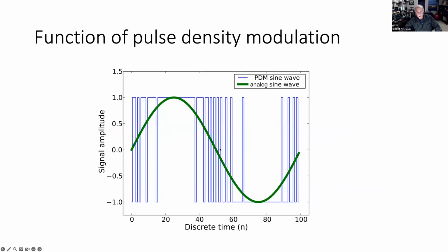So again, this is another view of that, where the pulse pattern, in this case, I think, is a pulse frequency modulation, where now you're not modulating the width of the pulses, but you're modulating the frequency of the pulses. So that can change according to what the sine wave is doing. This is a pure sine wave. Now you can imagine if you modulate the sine wave, say with amplitude modulation, then the pulse train will follow a more complex wave, but it will still follow the sine wave. So it's the amplitude of the sine wave that will determine the frequency of the pulses in this case, or in the previous slide, the width of the pulses.